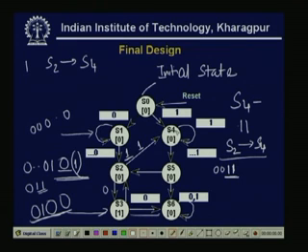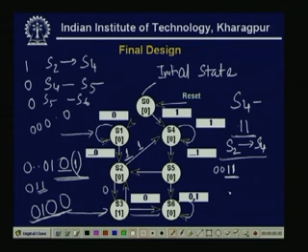Then any number of 1s we have seen stays in S4. So if a 0 comes, it goes from S4 to S5. Now again if a 0 comes, it goes from S5 to S6. So our S6 state recognizes, if we consider 3 consecutive input bits, 1 0 0.